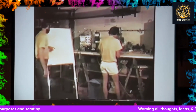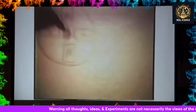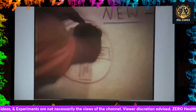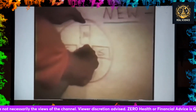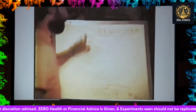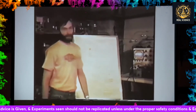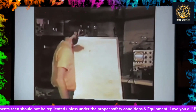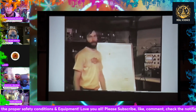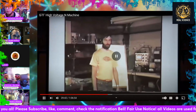I'd just like to say that basically, for the first test you just saw, we had one brush on the shaft here, and another brush riding on the disc out at this location, so that as the different pole faces move past between these two brushes, they produce EMFs in opposite directions, as would be expected. What was interesting about this is that it produces any EMF at all, because all of the points on the shaft that would be producing these things are in direct short circuit with each other at an extremely low resistance. Peter, is the frequency deemed by...